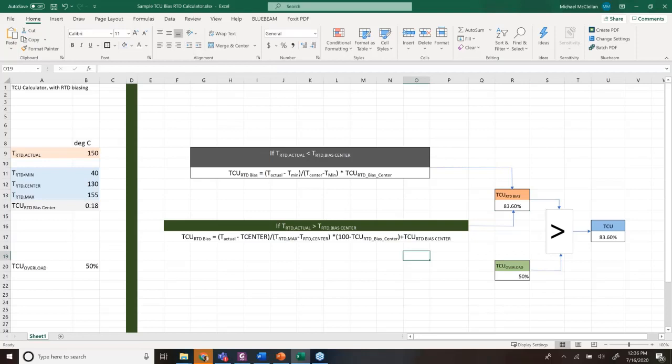And so, why don't we take the case of the fan being installed backwards. Let's say we're running at steady state, and maybe our thermal capacity used in that motor, if it's been started across the line, and it's been running for, say, an hour. The thermal model would tell us that the thermal capacity used has decayed quite a bit, and it's close to the steady state thermal capacity being used. But that's not the case in reality, is it? Our fan is on backwards, okay? So